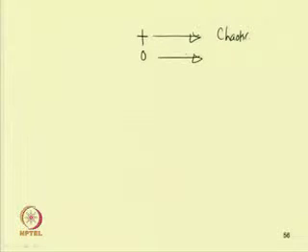If one has a one dimensional map, one can have one positive Lyapunov exponent or one 0 Lyapunov exponent. In case of a positive Lyapunov exponent, one can tell the response to be chaotic, and if the Lyapunov exponent is 0, one can tell that it is marginally stable, and if the Lyapunov exponent is negative, then one gets a periodic response.